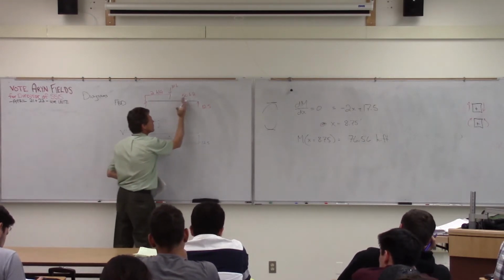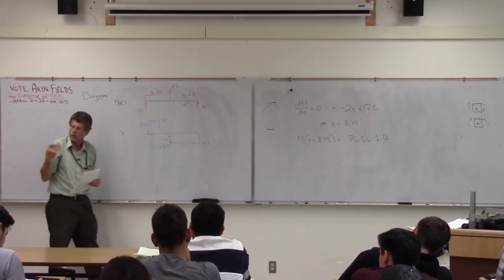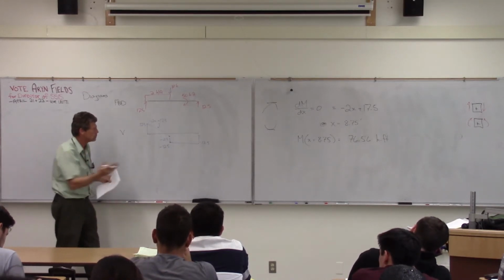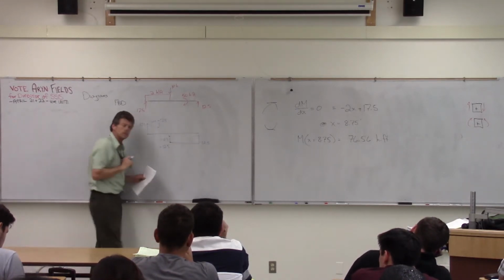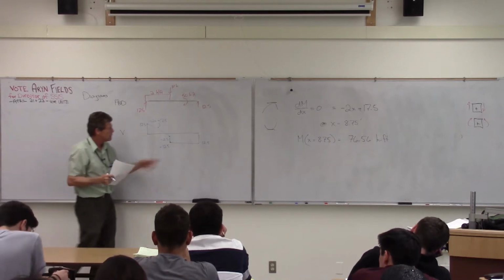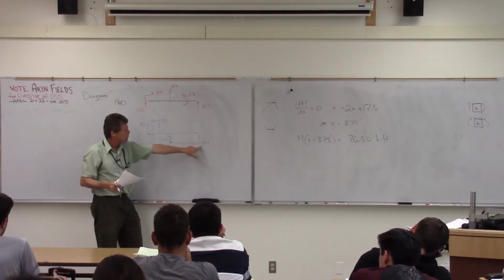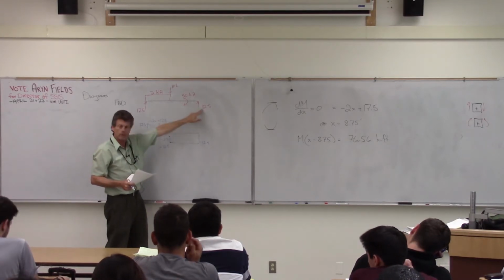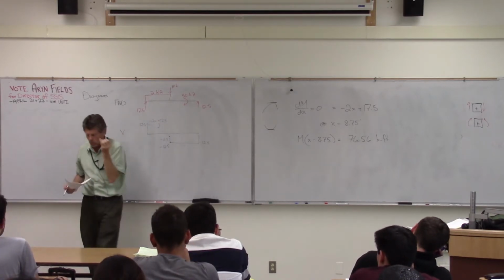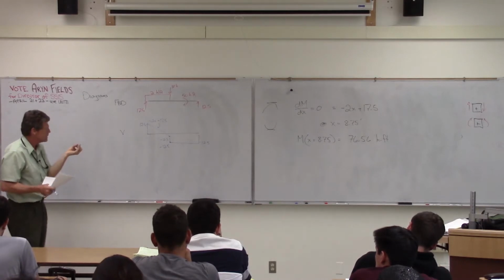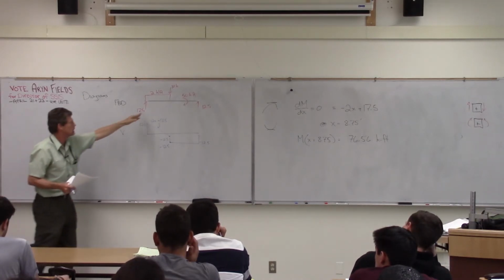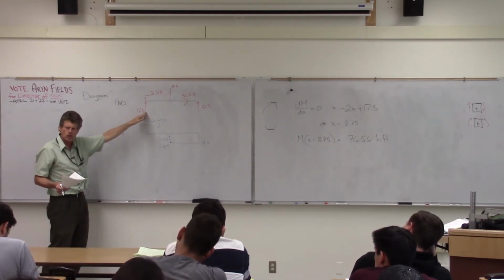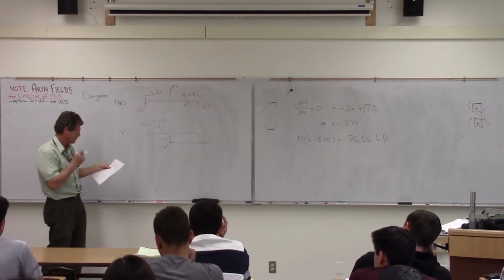And then as I go across here, yeah, I have a concentrated twist, but that doesn't have anything to do with vertical equilibrium. It's happy, and it just keeps at that minus 12.5. The end point, minus 12.5. Looks pretty familiar. Again, it's that jump. So when you draw your shear diagram, you always need to think about it in terms of the free body diagram. Think about it in terms of forces, not in terms of supports.